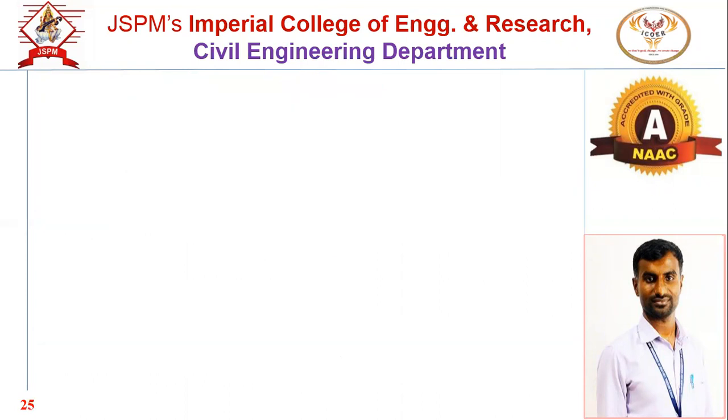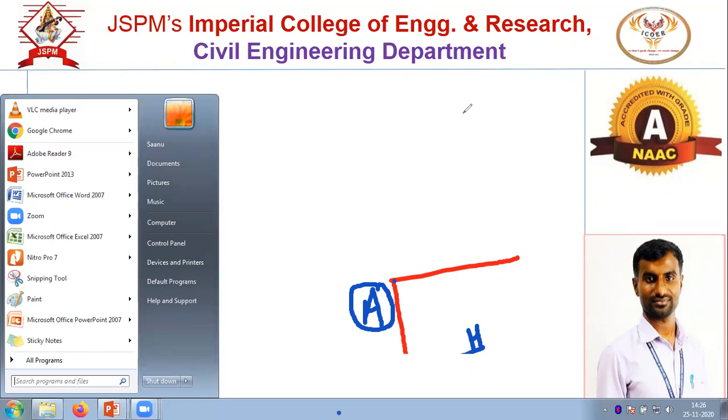Now, in case of portal method, if I draw the FBD of one joint in case of portal method, suppose this is the portal method, and this is the value of h. That h we have calculated using summation fx equal to 0. Now for this joint A, tell me how many unknown forces are there, maximum unknown forces in portal method.